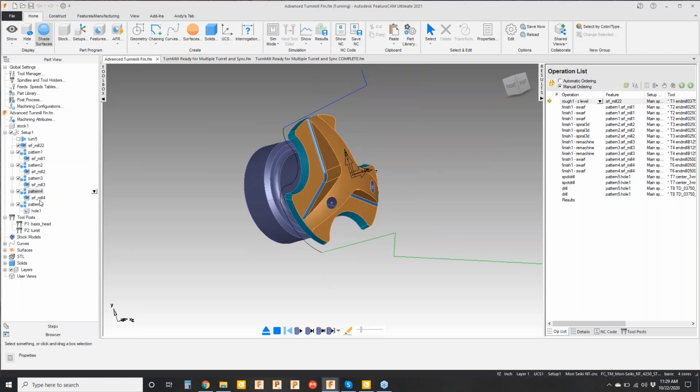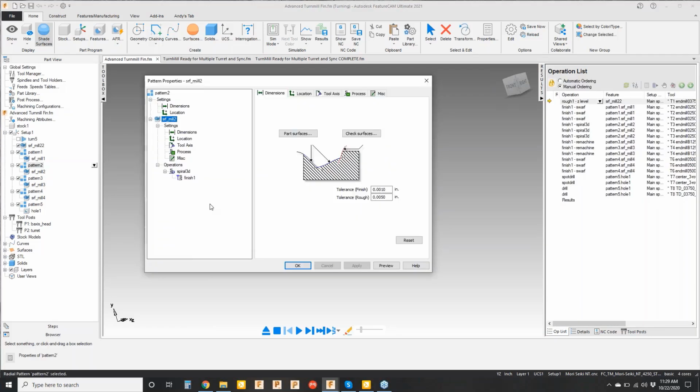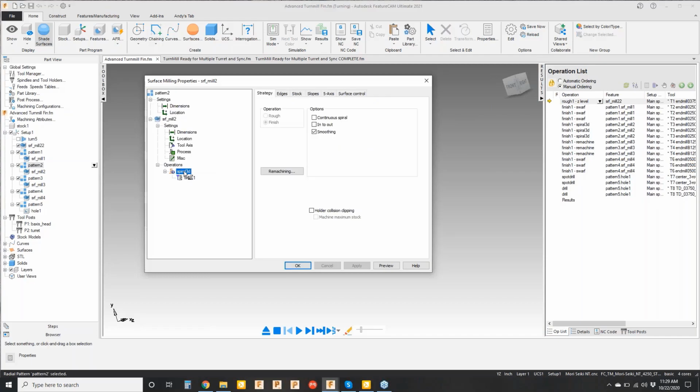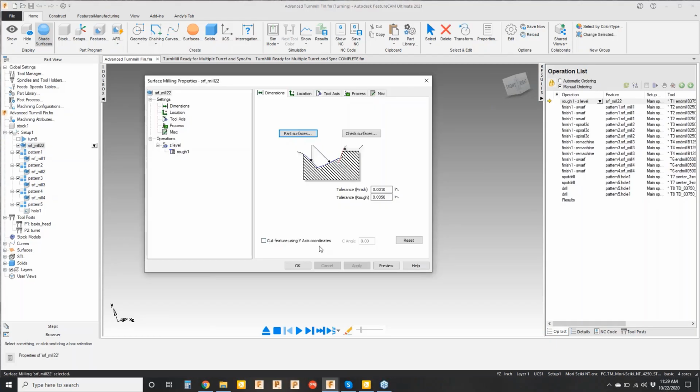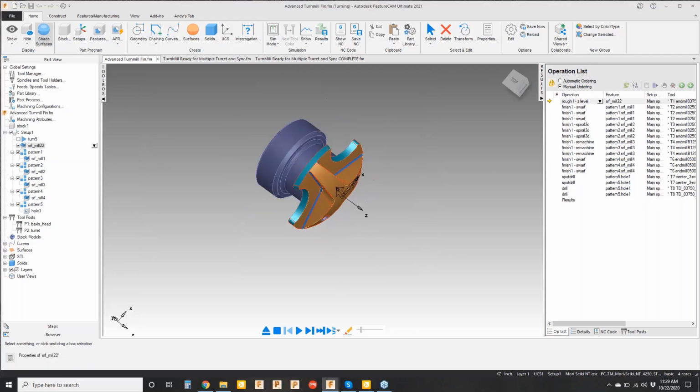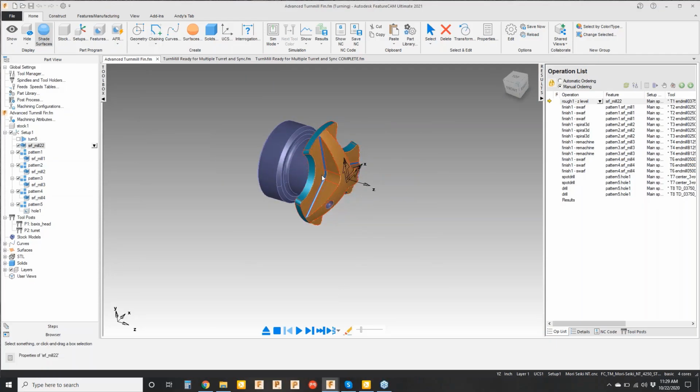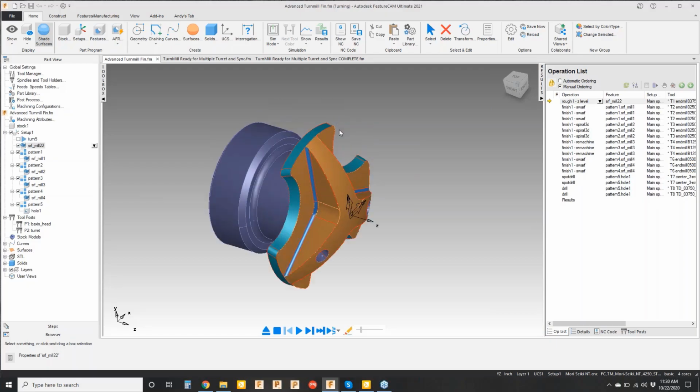And you could do the whole thing, or you could pattern it like we did here if that's what you want. But the C-axis thing I mentioned a few times, I just want to show you guys on here that some of these toolpaths, you have the ability to do that. So the Spiral 3D wasn't using it, but if we go look at the Z level right here, you see cut with Y-axis instead of the C, so you're getting XYZ instead of XZC code, and so forth. So the capabilities that you have in here are really immense. Something you should consider if you have parts any similar to this.